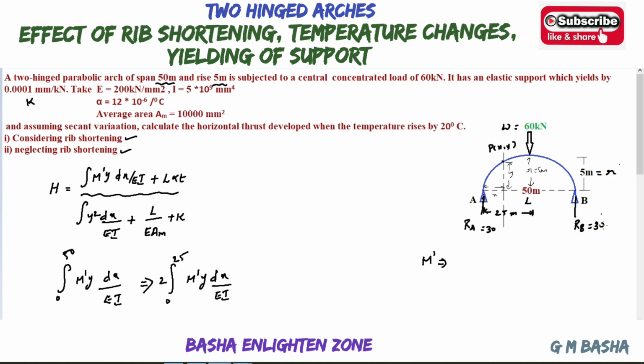Whenever a point load is acting on the arch, based on the simply supported condition, on a simply supported beam the load will be distributed equally, that is 60 by 2, 60 by 2. Then what is your M dash? Moment M dash will be equal to RA into x, force into distance. Force is 30, distance is x, so that is 30 into x.